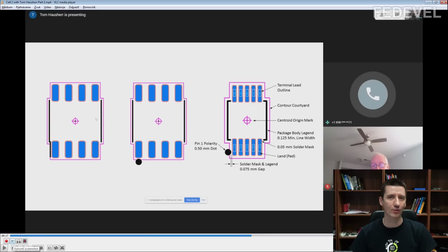So always when you finish your PCB, don't forget to check your mask layer and silkscreen layer together, so you are sure the silkscreen layer is going to look as you would expect, or the legend is going to look as you would like to have it.